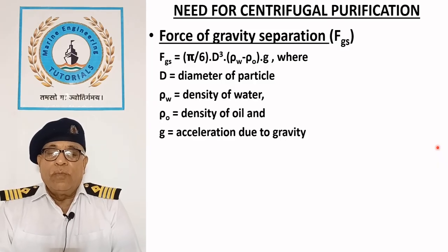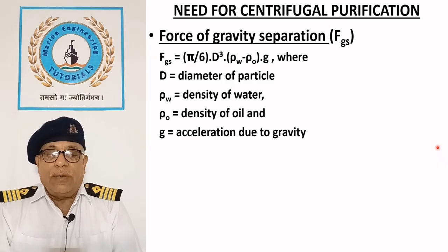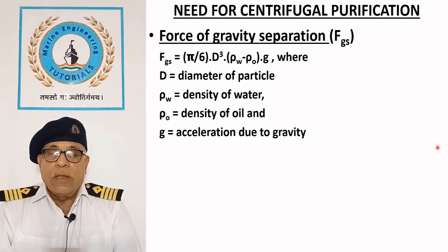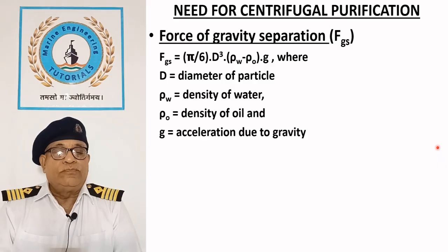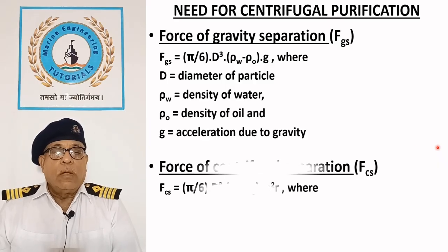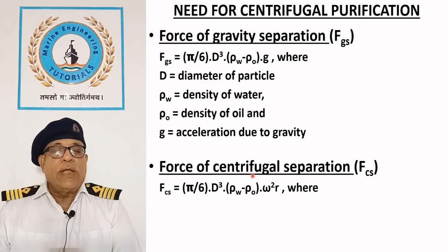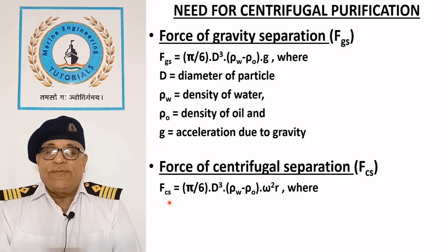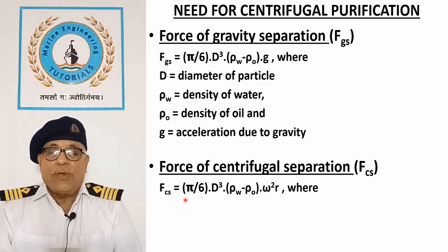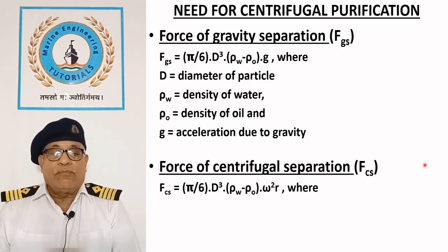Centrifugal separation increases the force of separation considerably, which is described below. Force of centrifugal separation, FCS. The force of centrifugal separation FCS is given by the equation FCS = π/6 × d³ × (ρw − ρo) × ω²r, where